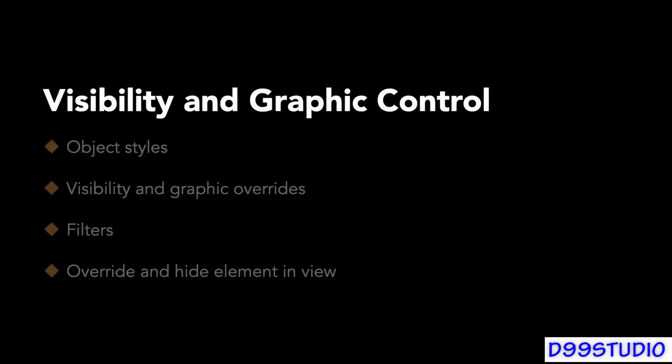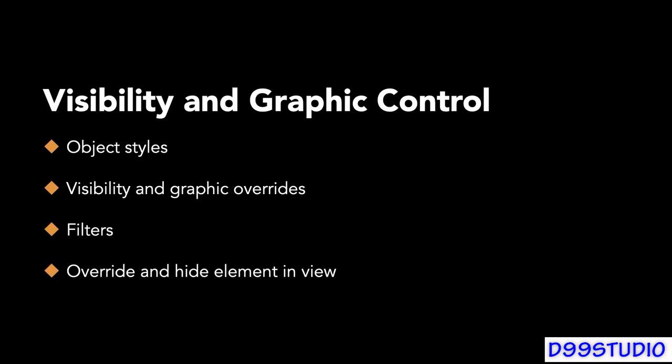The specifics of controlling the view extents will vary slightly by view type. Elevations and sections are easily manipulated with on-screen controls, for example, but plans require a little bit more effort using the view range dialog. But once you're certain that the extents are correct for your view's purpose, you can move on to any required visibility and graphical customization.